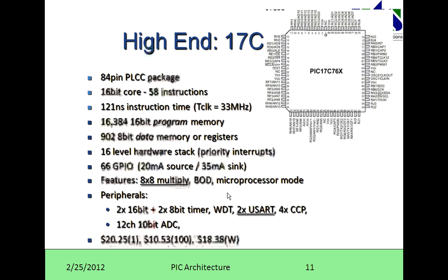So when you multiply 8-bit into 8-bit values, it will give 16-bit results. So there are no 16-bit registers, right? So any processor which supports 8 into 8 multiply, there are some registers, high and low register. That means two 8-bit registers which store the result of 8 into 8 multiply values. Okay, and it executes the 8 into 8 multiplication in a single instruction.